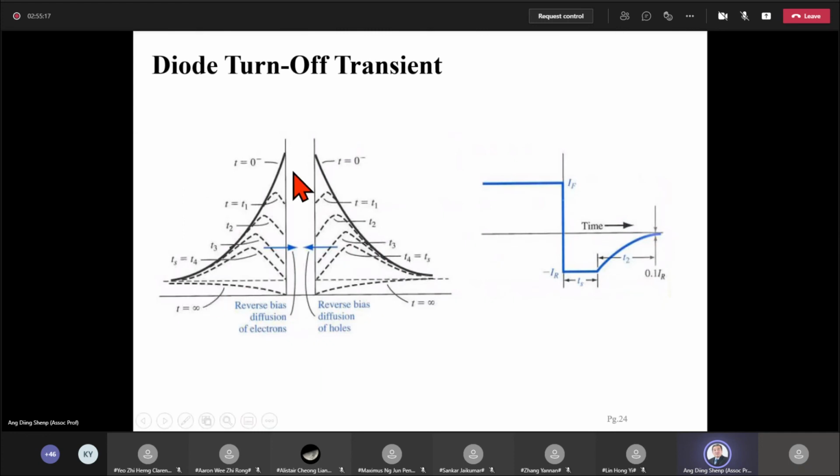Before the concentration reaches equilibrium, and once it drops below that, the current will start to decay significantly towards the reverse saturation current value, which is controlled by the slope of the minority carrier profile here. Oh, okay. Thank you. Okay, thanks.